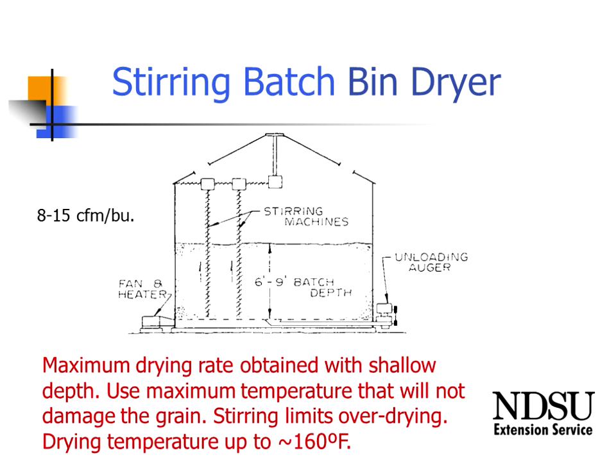The way to get the maximum performance out of that type of drying system is to keep that depth shallow. They may tell us that we can add more depth in here and use this as wet holding, but when we do that, we're going to reduce the amount of airflow and reduce the drying capacity considerably.